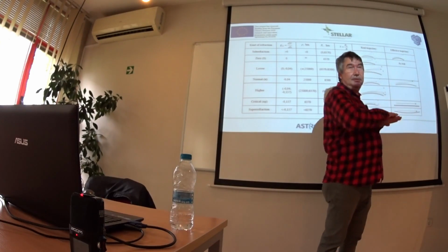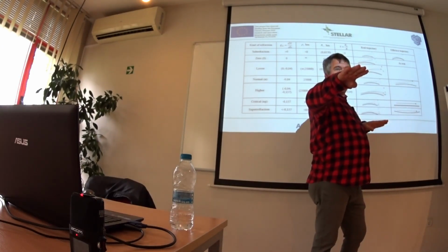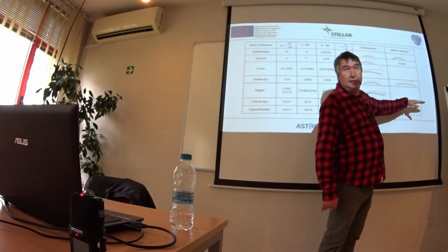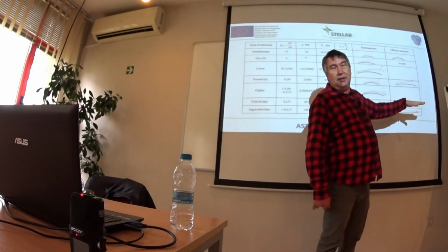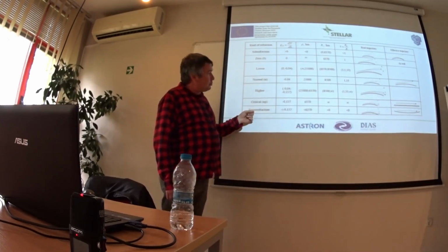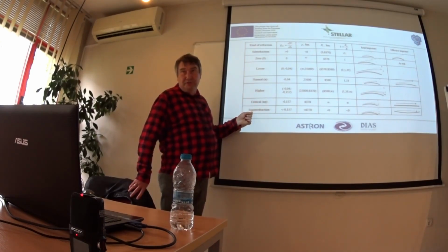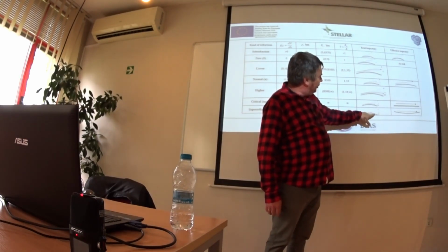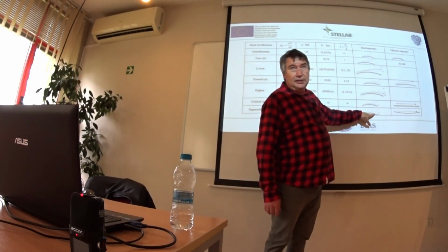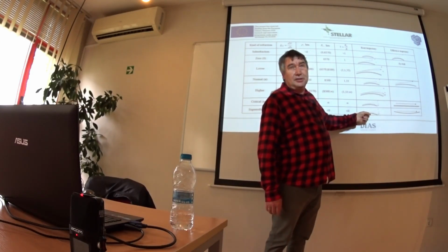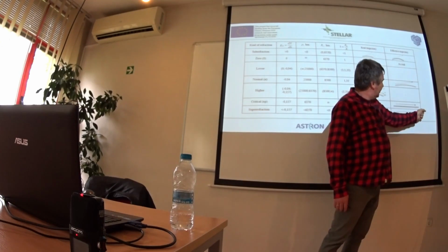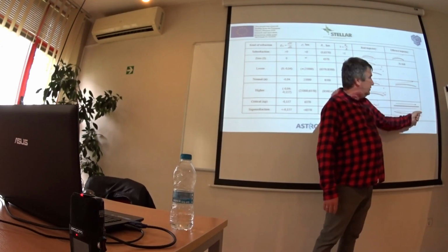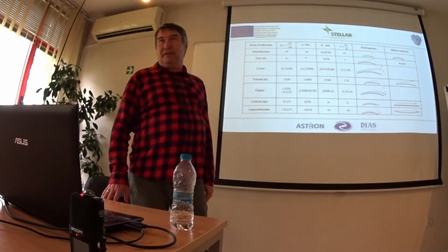The Earth surface is a plane, and the radio wave propagates over a plane surface. And the last one is super refraction. In this case, the radius of the wave path is smaller than the radius of the Earth surface, and this is the equivalent Earth, and this is the equivalent path, the straight line.